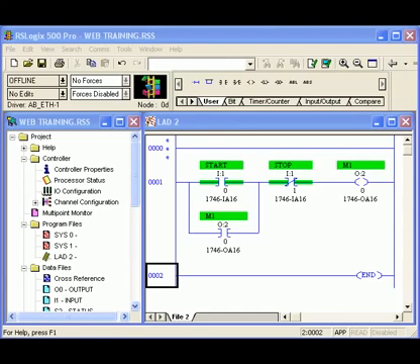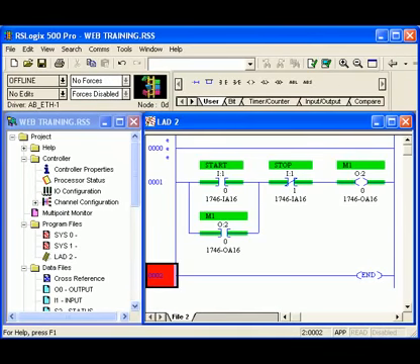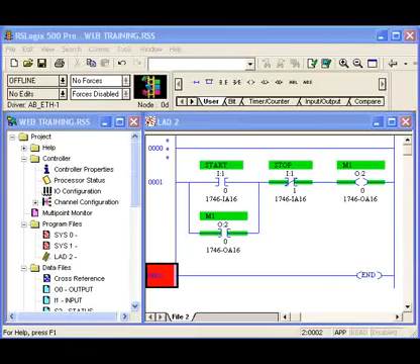If you look at this frame right here, you'll see that the start push button is pressed, so we have power made to that coil, and that coil will immediately go on. Now the coil is on and the start push button is still being held, and we'll be able to watch it go from on to off as the operator lets go of the start push button. So we have a situation now where our contactor is pulled in, and it's going to stay this way until our stop push button is pressed, removing power from that part of the rung.